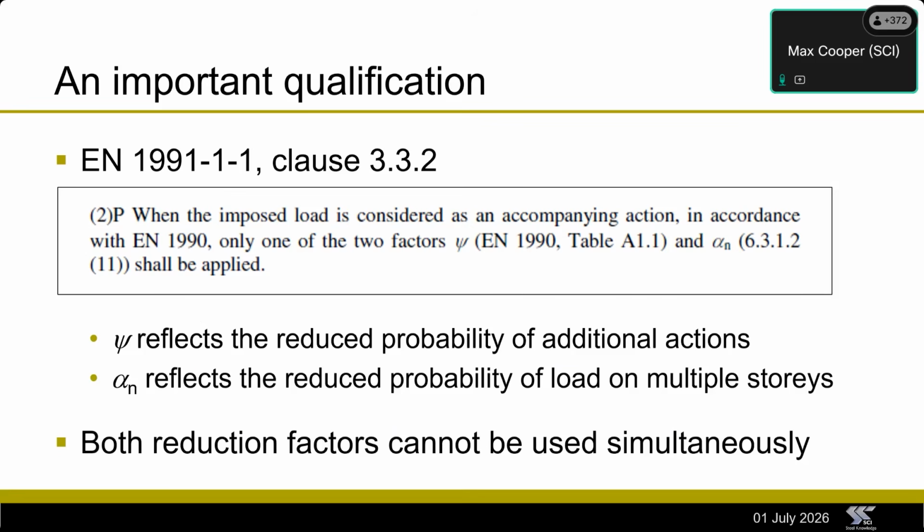One thing to draw your attention to is that in EN 1991 Part 1 Clause 3.3.2, you are not permitted to combine the psi factors with the area reduction factors, or the story reduction factors. So you have to pick one or the other. But I think when you're considering these as not the leading action, I would suggest that it's unlikely to make any difference to your calculations anyway.